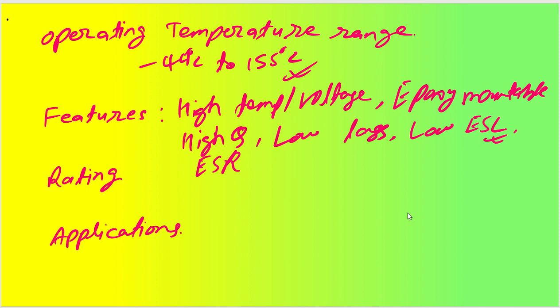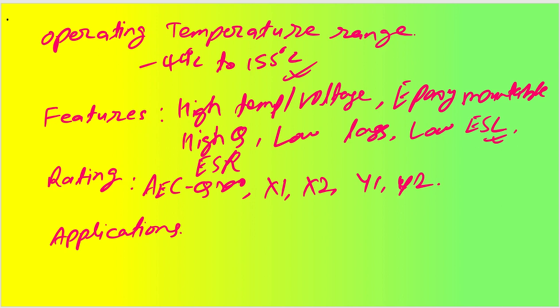Now coming to the ratings. So what are the ratings that we can look ahead? If you want to utilize it for automotive applications and all, then you definitely will look ahead with AEC-Q200, right? AEC-Q200. Whether you want it for some safety capacitors like X1 or X2, Y1 or Y2. So all these features you can look into for your capacitors.